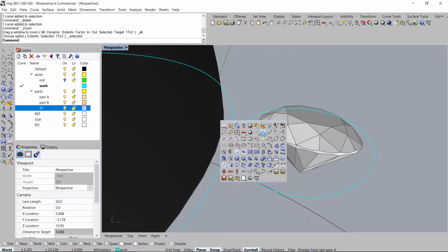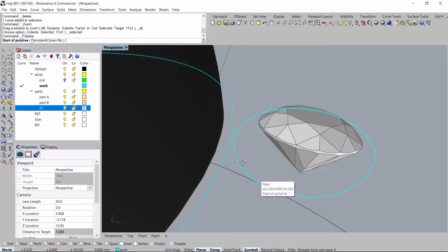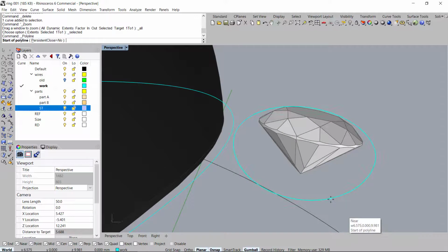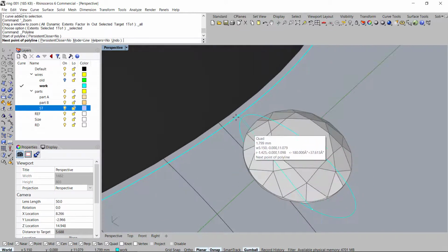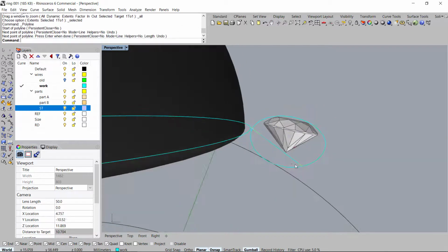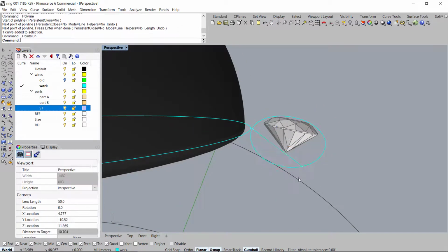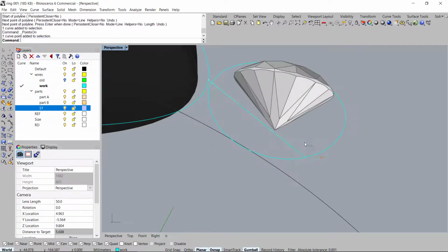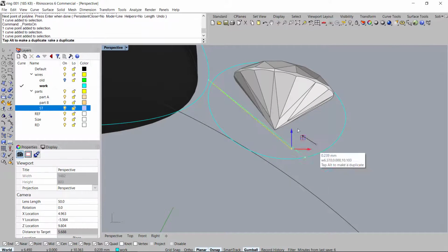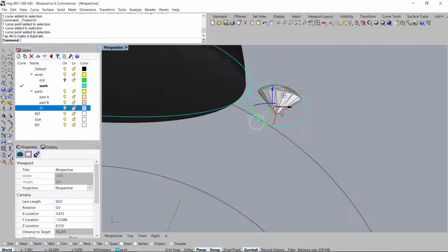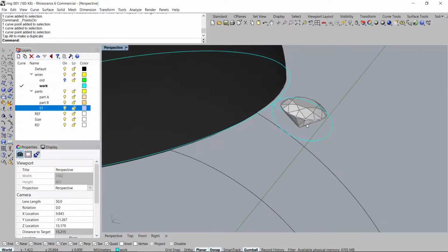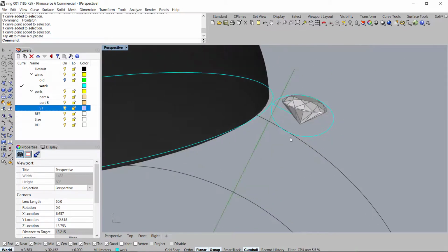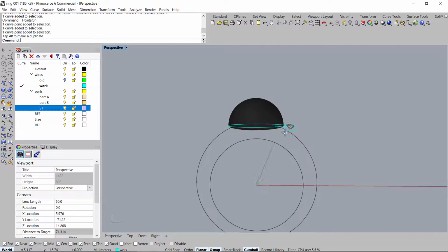Let's go with the line tool again. I'm going to snap it to the center. If I can't find the center, just put it anywhere on that line. And we're going to look for quad, just like that. We'll select the line, hit F10, and I'm going to move it right inside the middle there, just like this. The reason why I did that is because I want to create an actual curve that's going to establish our body here.